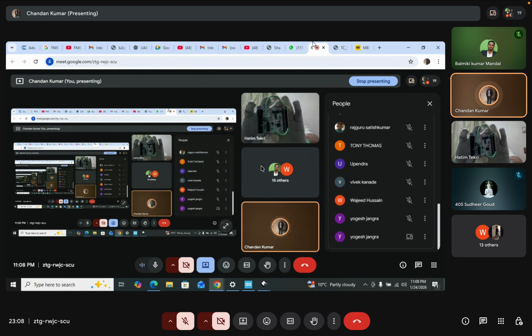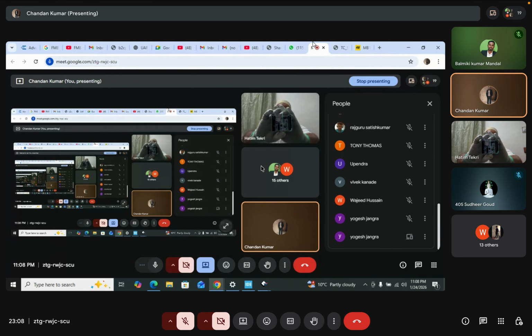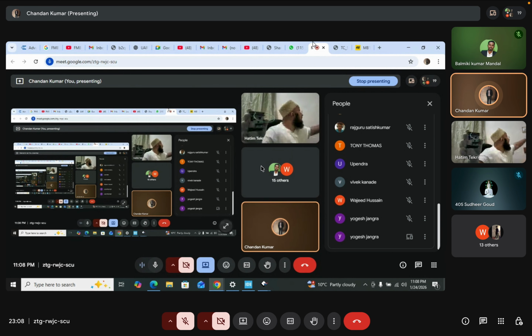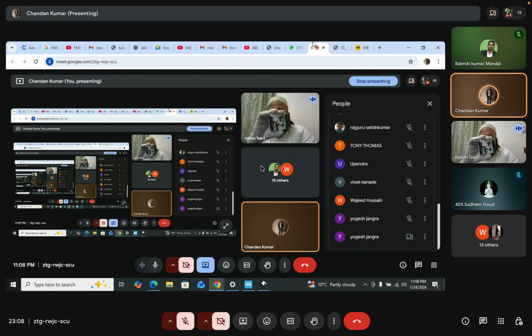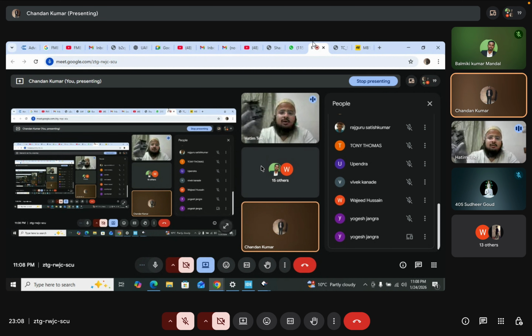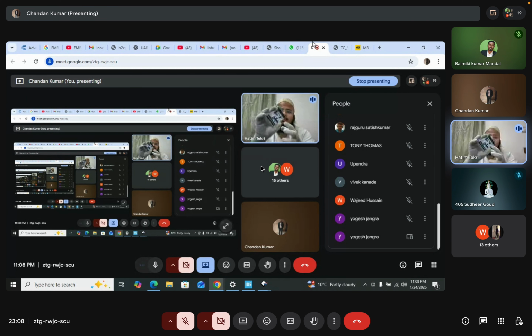So whatever we transmit from our TX pin, the same data will be received on our RX pin. Fine. So just debug the code or just run the code that I have written just now. But I think for that I have to connect the ST-Link wire. Yeah. Now you will connect it.